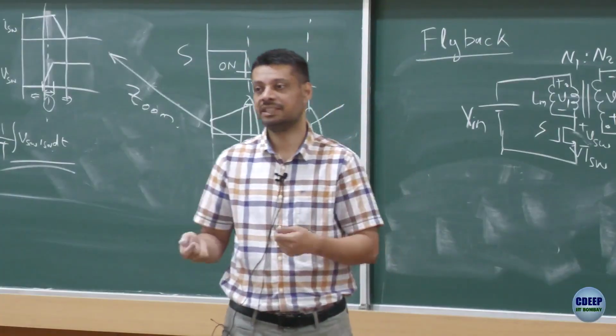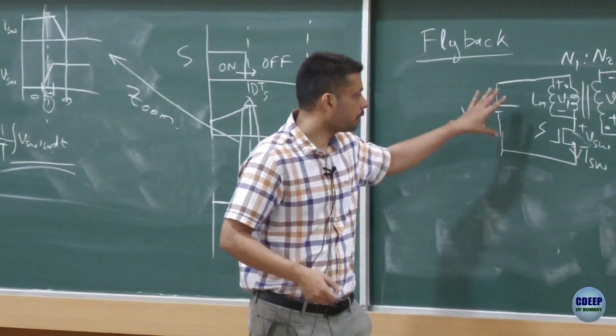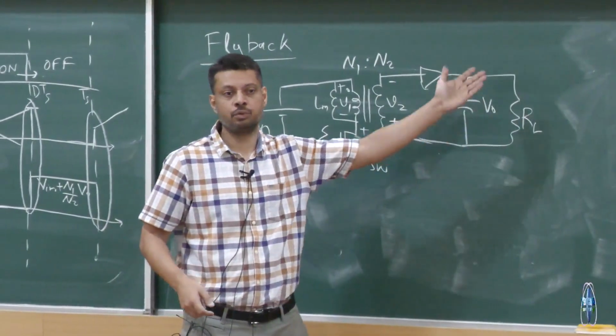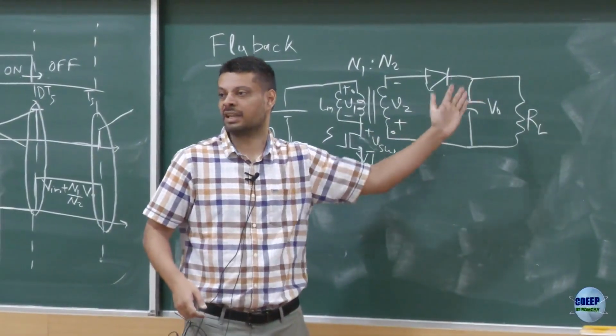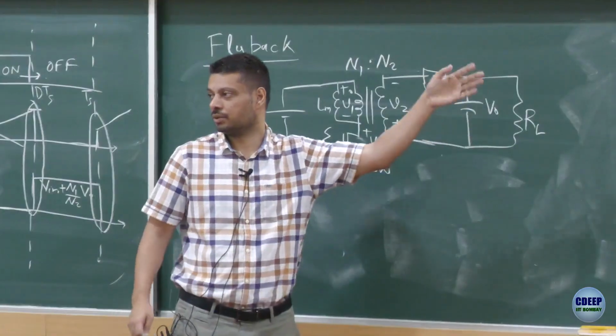Now how do you achieve those? One option is you use a flyback circuit, right? From 400 volt you get 5 volt. Now you can do a 5 to 12 boost. You can get 12 volt, you can do a buck, you can get 3.3, and then you can try to create the others.